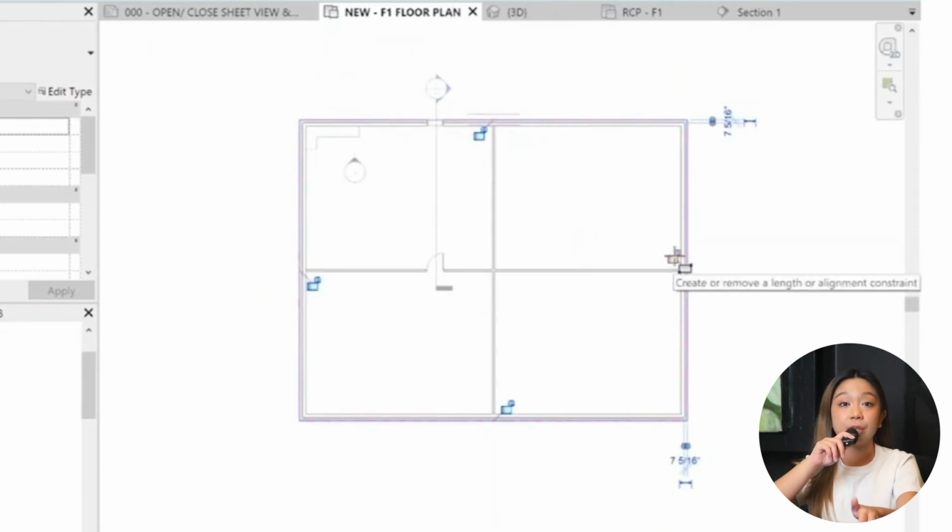As you draw the floor, you'll see small lock icons. These allow you to lock the floor to the walls, so if one moves, the other updates immediately. However, use this feature cautiously. Locking can sometimes cause unexpected issues like items being deleted.